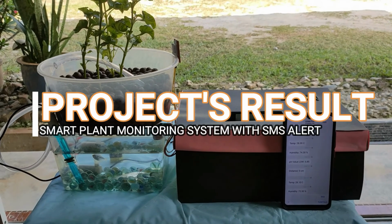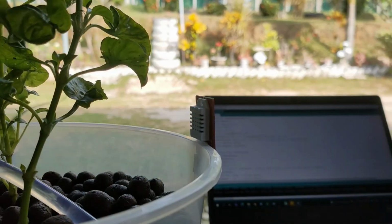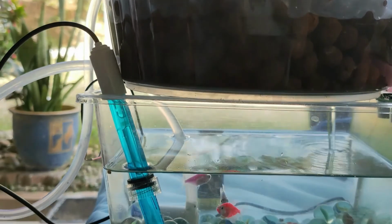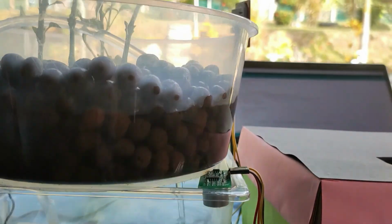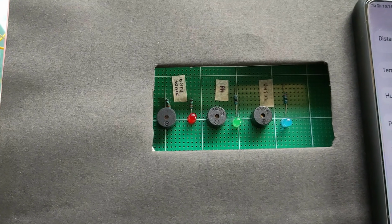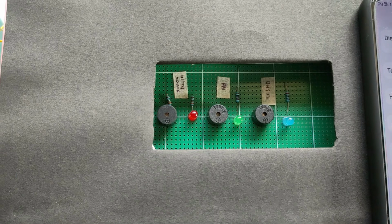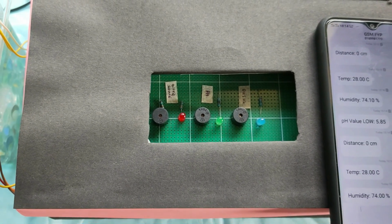This is our project, which is Smart Plant Monitoring System with SMS Alert. The process in this project is that all the inputs, the DHT22 sensor, pH sensor and ultrasonic sensor, will scan and send the data to the Arduino Mega and GSM module. After that, all the data will be displayed on the LCD I2C. Then, the buzzer and LED of every sensor will be turned on if the data is more or less than the average value. The function of these buzzers and LEDs is for the farmers to detect the condition of their plants.